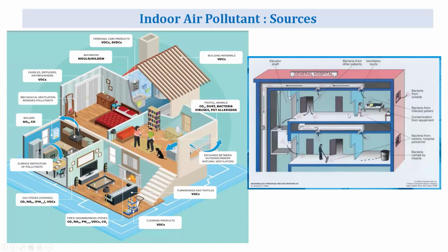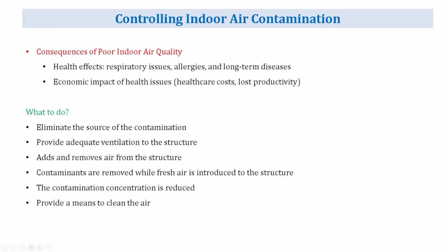So you need to be very careful. This is a very small step which doesn't require any additional cost when you're planning for HVAC or things like that. You need to make sure that you are taking the air from the cleanest point of the building. It may be upside, it may be this side or that side, but not on the side where the contamination is pretty high.